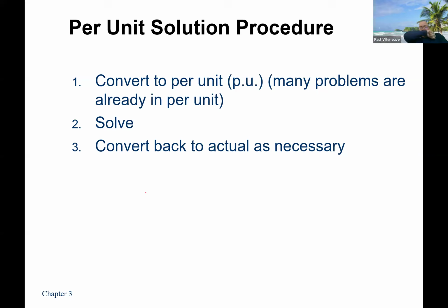So if the voltage is 0.8, then I've got a problem. That's a pretty serious voltage drop in my system, so I probably need to start looking at it. So generally speaking, voltages you leave as per unit quantities. Power, sometimes you will convert back to megawatts or MVA.